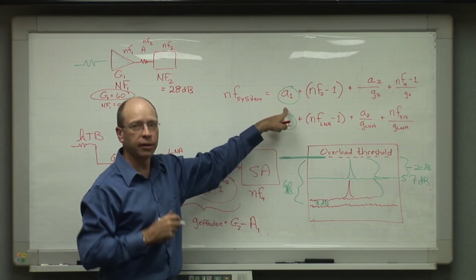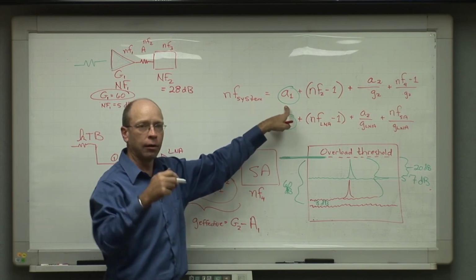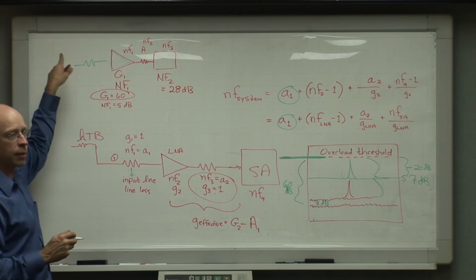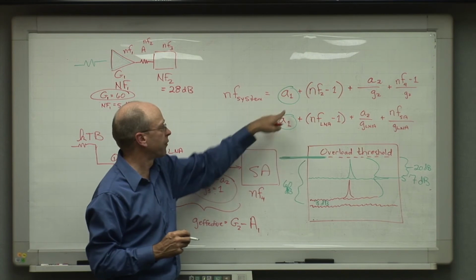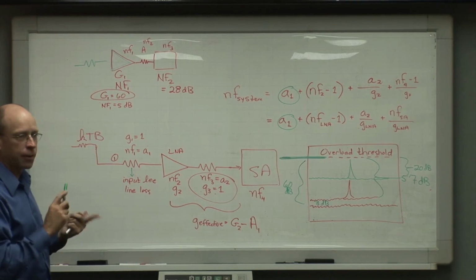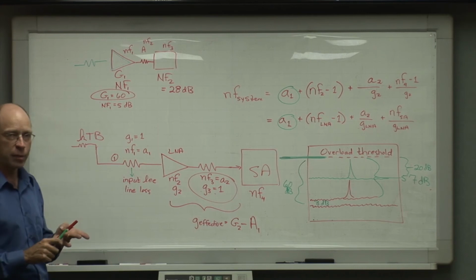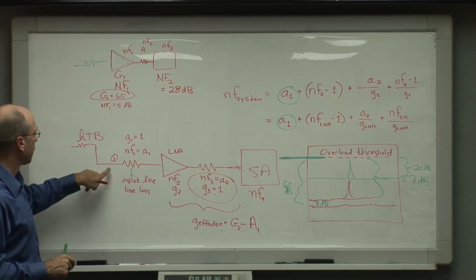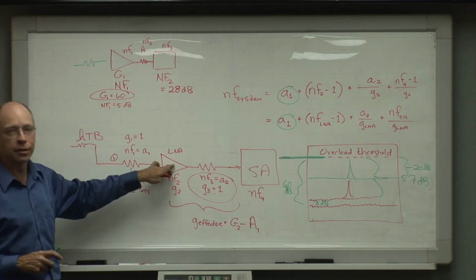They know it's a good practice to do it for a variety of reasons, but they know that whatever the loss in that filter is, it's going to add directly to the losses in the rest of the system. Likewise, if we're connecting the system up to an antenna and we have a long line going up here and the line has a lot of loss in it, that line loss is going to add directly to the noise figure or the noise factor of the system. So what people try to do is use the lowest loss lines possible or the shortest lines possible, and if they do need to put a filter in, they'll try to get the lowest loss possible in the filter and so forth, because we can imagine a filter along with a line, along with maybe even something else in it. All those losses add up until we finally get to the low noise amplifier.